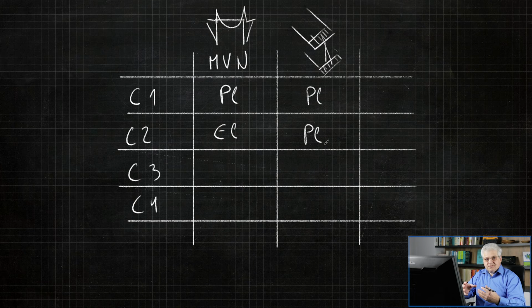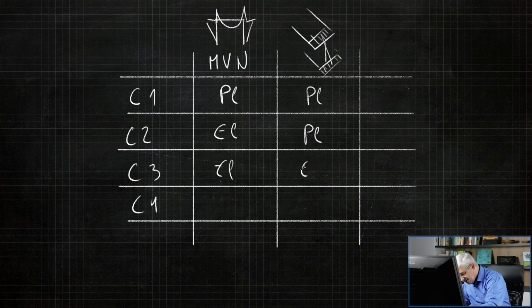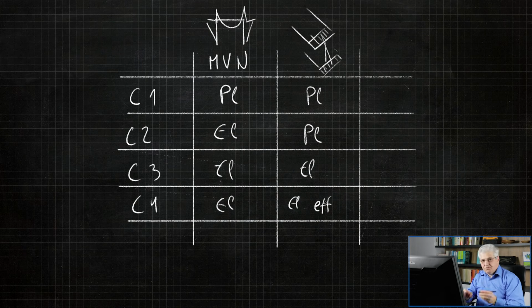Class 3 has again a little bit less rotational capacity, so we can analyze the cross-section with elastic properties and check also with elastic properties. So we have elastic and elastic. And then we have class 4. These are cross-sections that have stability issues at some parts. For example, we have a very thin web, and this thin web can get buckling from the load. So then we run also elastic calculation, elastic checks, but with effective properties of the cross-section, only the remaining part which is not buckling.